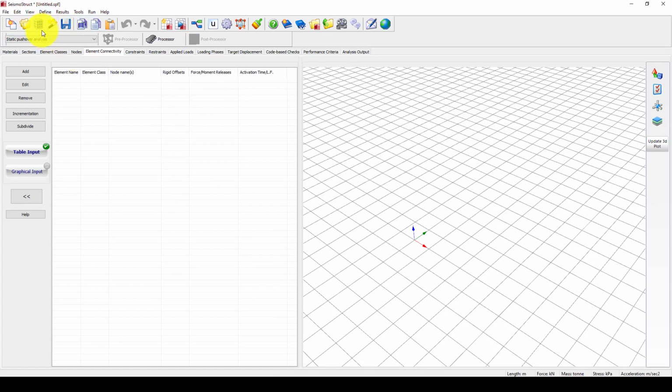So I'm going to select here, come to geometry, 400 by 400, and quickly model them. This is the column created, and now when I insert bracing or steel bracings, we don't need to add this infill panel.